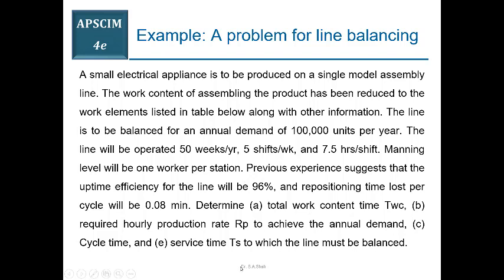And one thing more that I discussed in the previous video is that normally the cycle times are given in minutes, and standard for production rate, we normally calculate production rate in terms of hourly basis. So you have to keep that particular scenario in mind, that if the cycle times are given in seconds or minutes, you will have to convert that into hours.